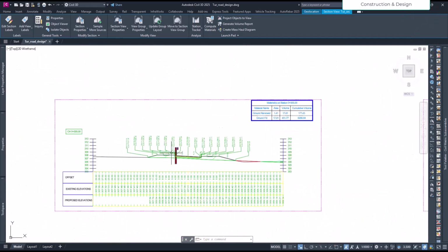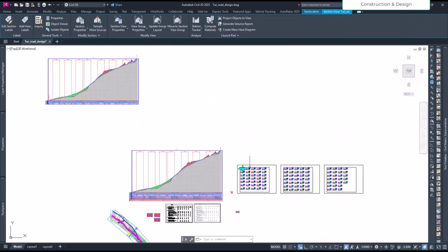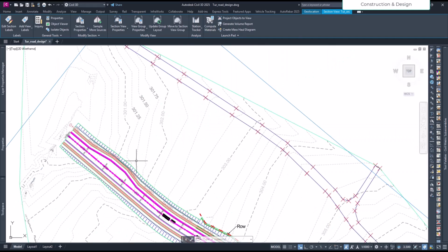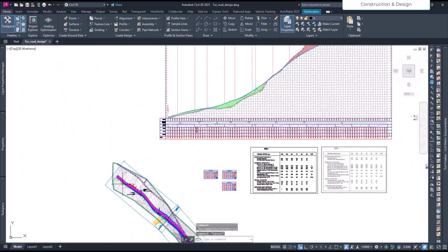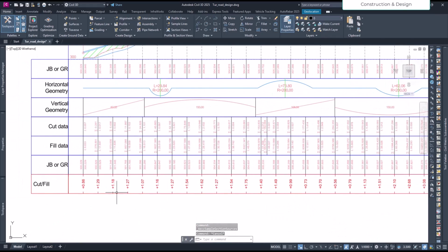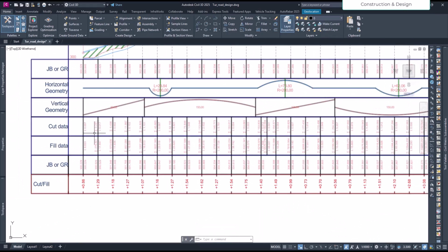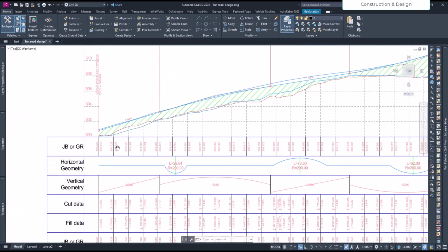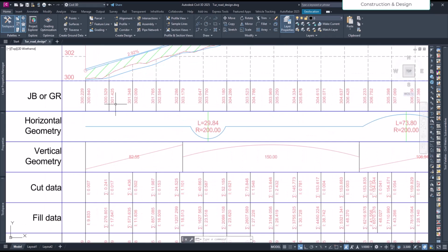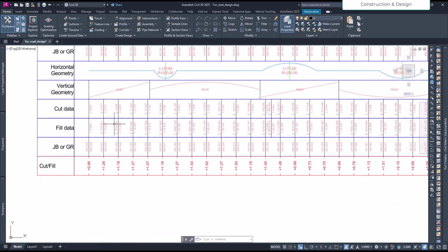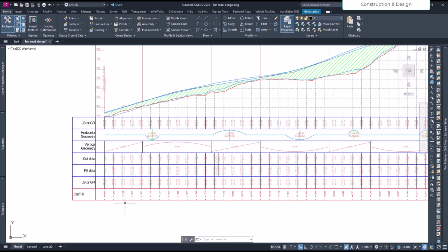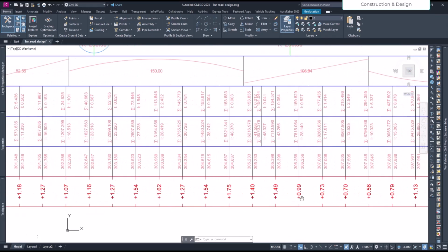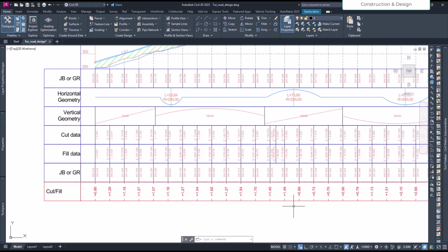But we don't want the guardrail to be everywhere, right? So what we have to do is check from here. You see, from this particular location, let's say this is chain edge. I think I have removed the chain edge, but still we can know this is 0, 20, 40. So 280 meters from here we have the guardrail, from this particular part, 20 to 280.